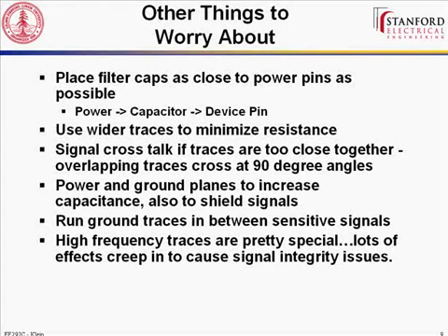So how much do you have to worry about the resistance? So the question is for this project, how much do you have to worry about the resistance? Not much. There'll be a few places where you do have to worry. You have to worry on the audio output going to your headphones. You probably want those to be fatter because that's actually driving power. You have to be careful with all of your power pins. Those all need to be as fat as you can without running into adjacent neighbors.